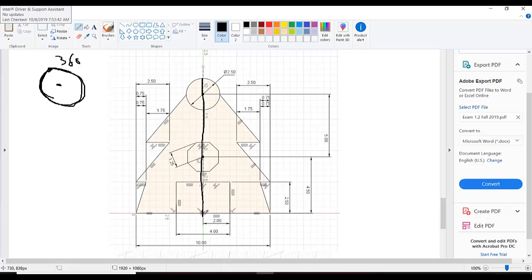For example, if we are going to design this half sketch, then for the dimension from this axis, the center of the sketch, from these points we need the half dimension. Like this dimension is 10, but around this axis we need the half dimension, 5. From here to here it will be 5, and this is 2, this one is 2.